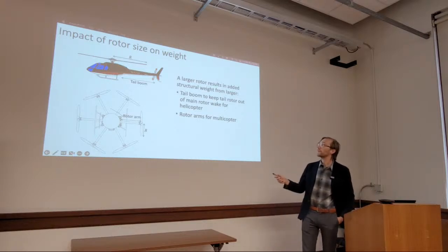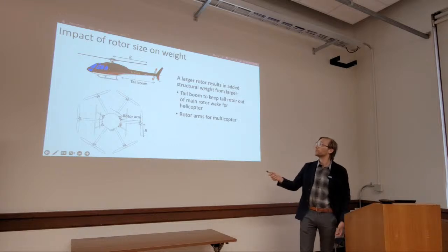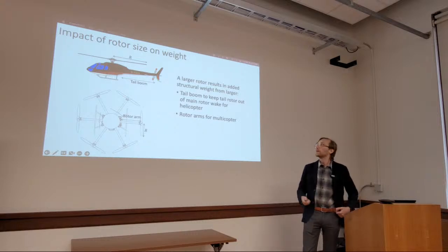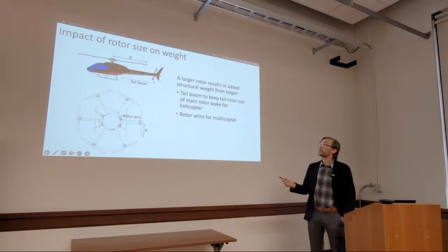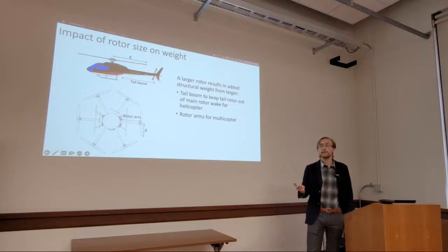To hold that tail rotor, we need a tail boom. And that tail boom needs to be big enough because we don't want the tail rotor to be under the main rotor. Otherwise, there's going to be some wake interference that will render the tail rotor ineffective. So a larger rotor means a larger tail boom, a heavier vehicle in the end.